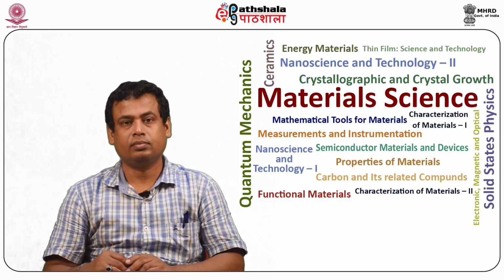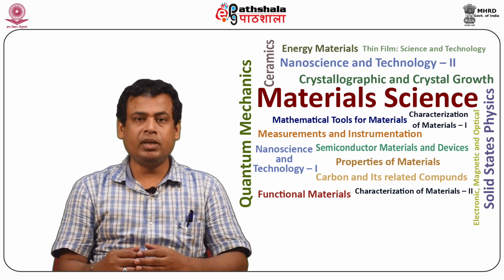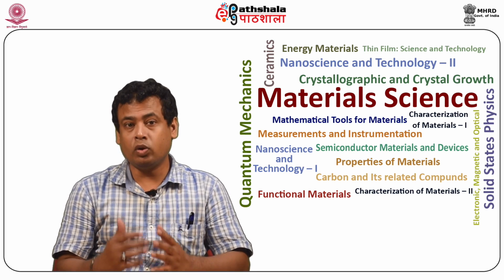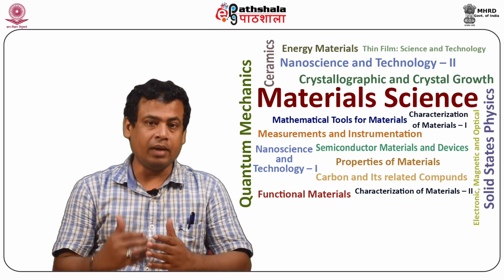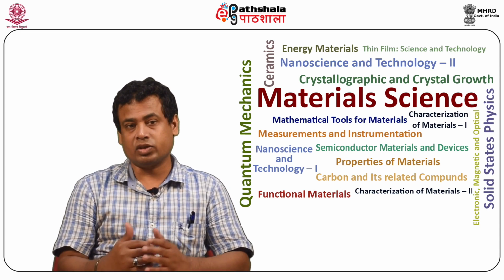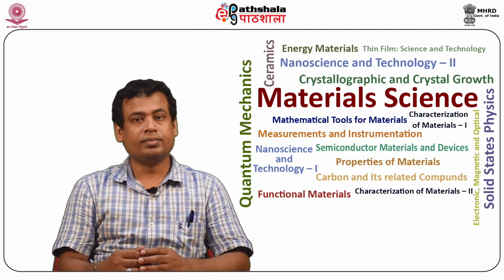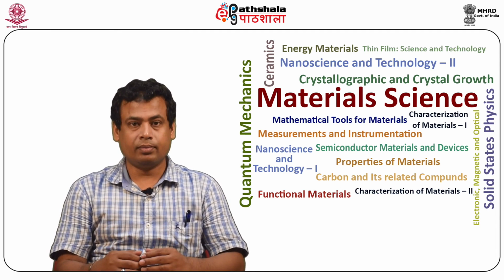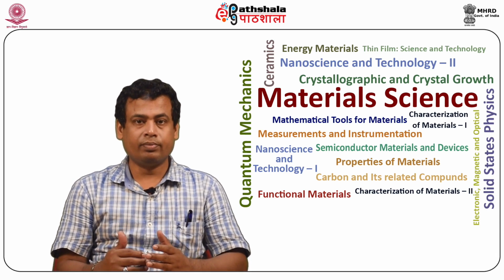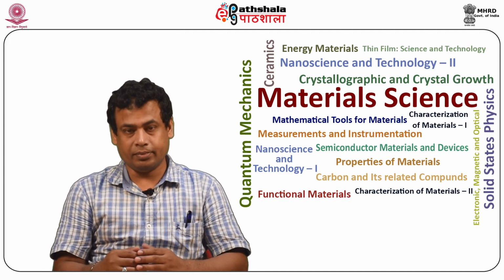below 30 nanometer. The electrons enter the resist and a few of them experience small angle scattering events called forward scattering, which tend to broaden the initial beam diameter, while some experience large angle scattering events called backscattering events. The backscattered electrons cause the proximity effect, where the dose that a pattern feature receives is affected by electrons scattering from other features present nearby.